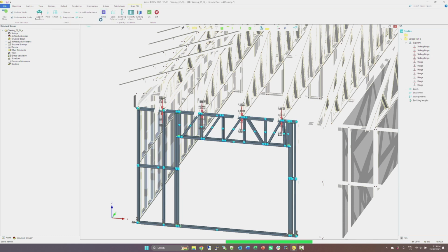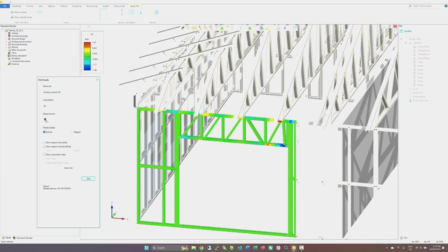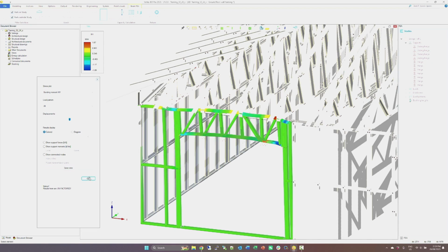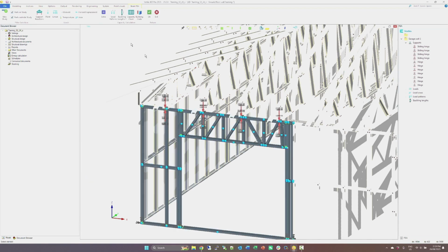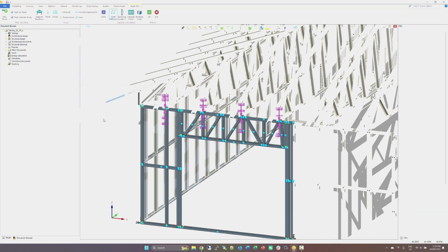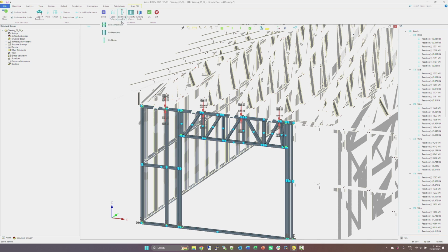I'll quickly just click solve so that we can have a look whether or not the displacement is reasonable. As you can see, the FEA solve is actually pretty quick because we only have beam members in our FEA study, so the solve is nice and easy. Now I will just create that same load pattern including all the loads in the study. Then define the buckling length. I can use also this by members function to define the buckling length.